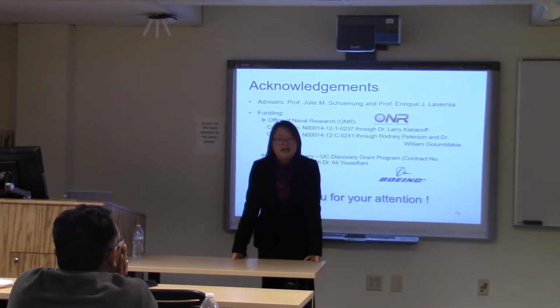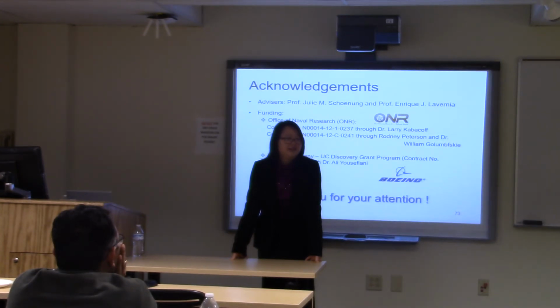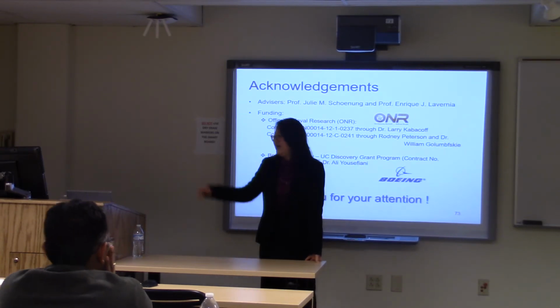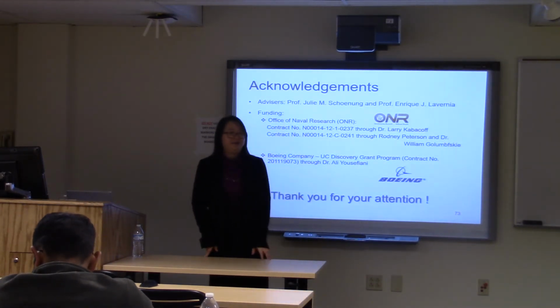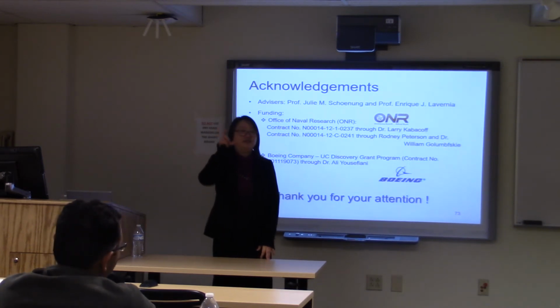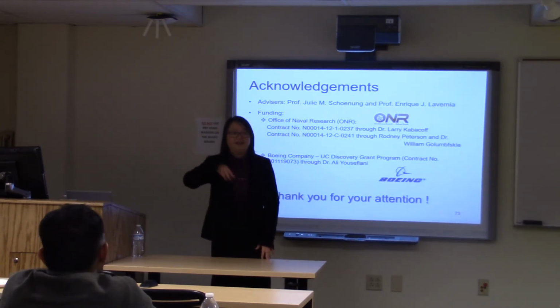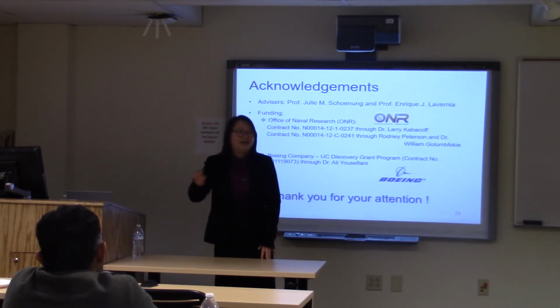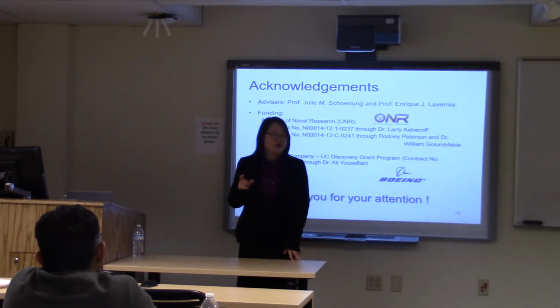Yeah, I have some work looking at the heat treatment, because my conclusion is those standard tempers probably don't apply to the ultrafine grain materials. I didn't put a slide here, but I have a paper talking about how if we shorten the heat treatment, not extend the time, shorten the time and lower the temperature, we will get more precipitates there. So we do need to think about the tempering, that's very good. You brought that up.